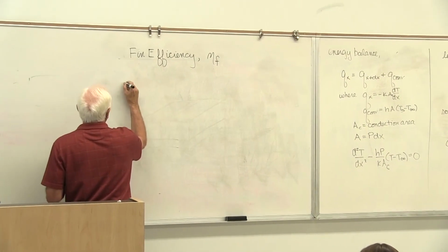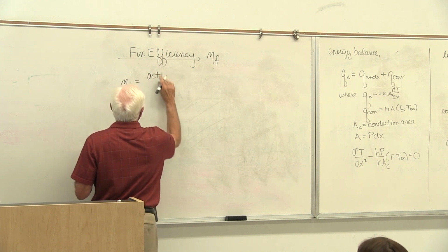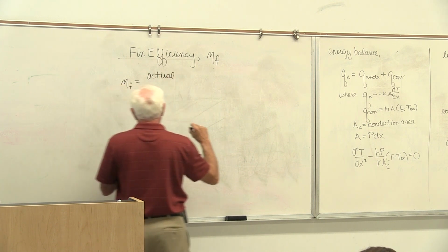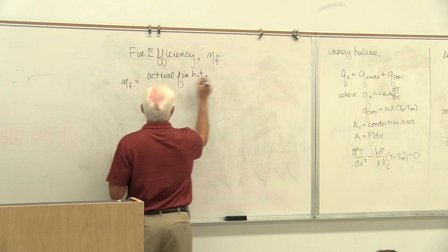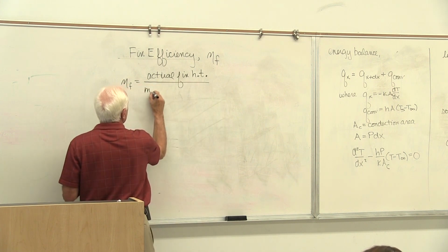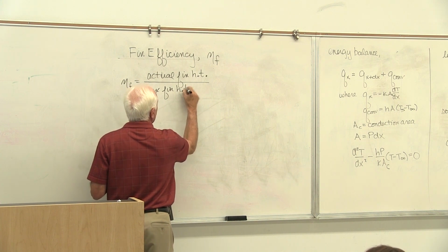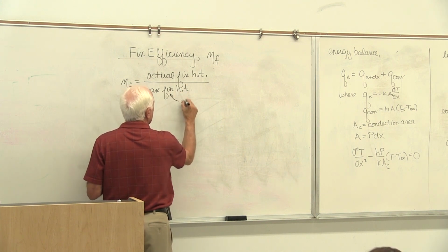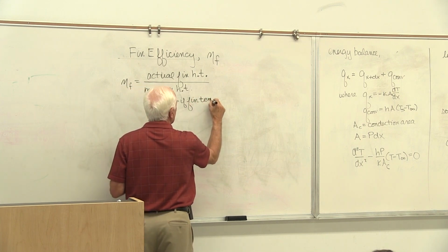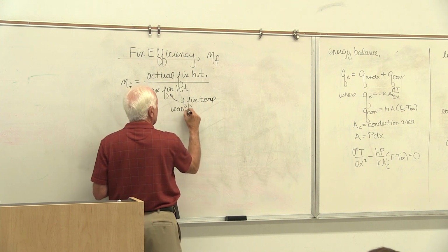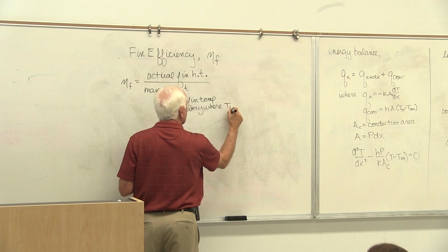Here's how it's defined. The actual fin heat transfer divided by the maximum fin heat transfer. And we define the maximum fin heat transfer as the heat transfer if the fin temperature was everywhere T base.